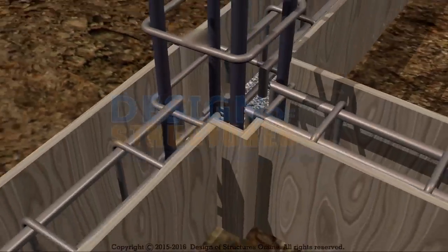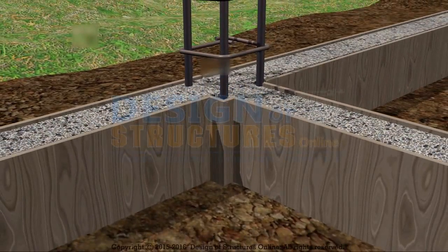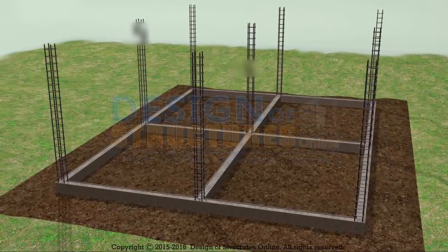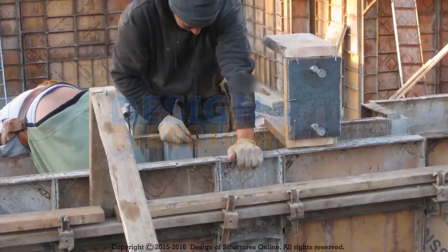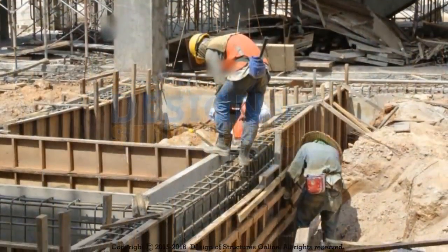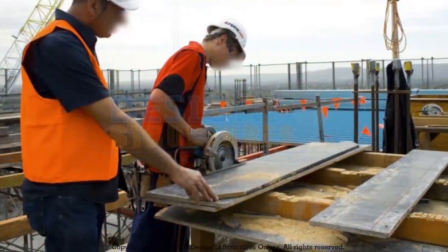Beam concreting. Beam is poured with concrete with the grade mentioned in the drawings. The positioning of reinforcement should be properly aligned. Shuttering parts and connections should be arranged in a way that makes formwork removal easy and simple, and prevents damage to concrete and formwork panels so that they can be reused without extensive repair.